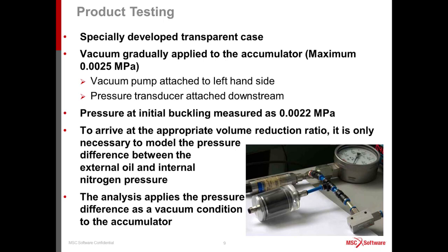Now, in terms of accumulator simulations, you don't actually have to simulate with pressure on both sides. What you're actually looking at is the pressure differential. So all we needed to do was simulate the collapse rather than actually the operating pressures, because the stress condition is the same. The analysis applies therefore a pressure difference as a vacuum condition to the internal surface of the accumulator, causing it to collapse on itself, and we're looking at the differences between the two.